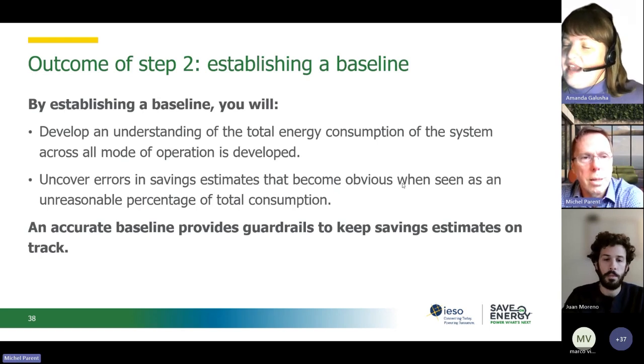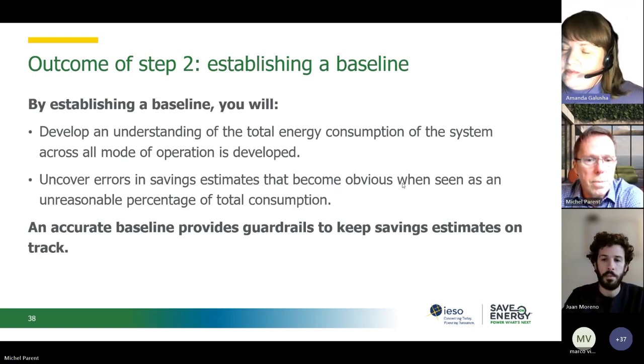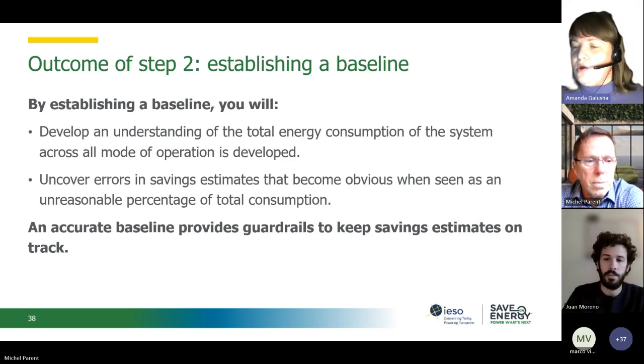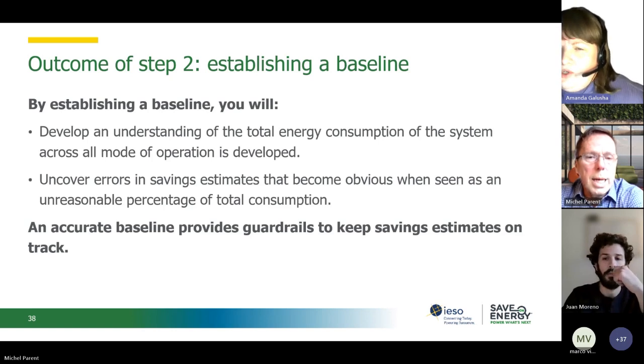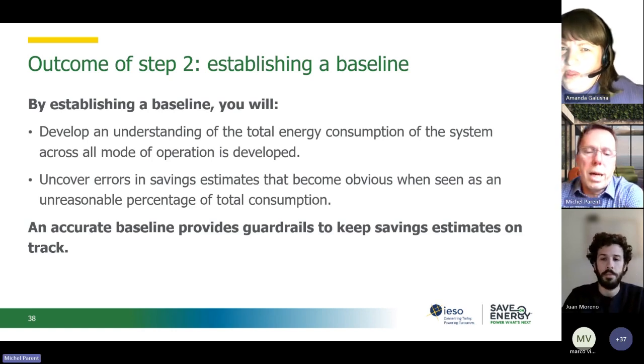A couple of questions. I think the one by Greg is specific to the equation being imperial, and so the 1.08 CFM delta T is an imperial equation that uses temperatures in Fahrenheit. So should this equation therefore use heating degree days based on Fahrenheit temperatures? Yeah, it would be all Fahrenheit.